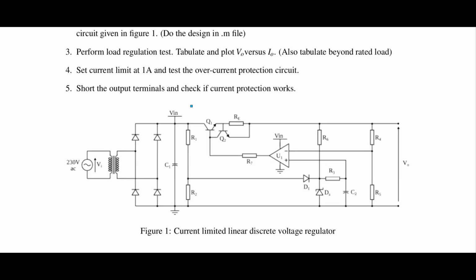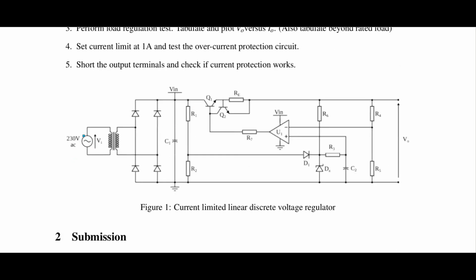So the linear regulator circuit, we have discussed this circuit. We have here the 230 volt AC and followed by a transformer. The transformer does three jobs here: scaling, the input output scaling, it gives galvanic isolation, and third, importantly, it also gives the inrush current limiting. And you have a rectifier diode, and this is followed by a capacitor filter, and this is the point which acts as Vin for the regulator. This is unregulated DC. And you have the series pass element here.